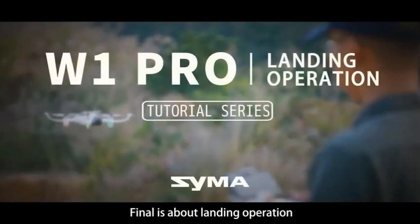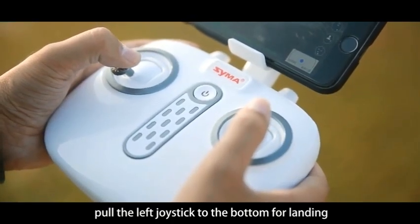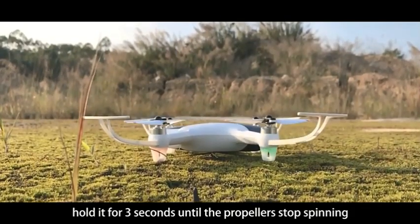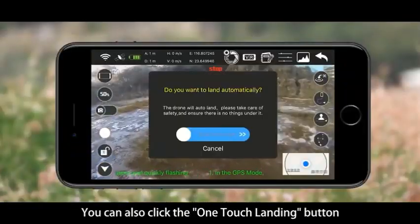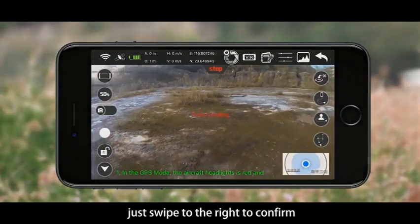Finally, the landing operation. Pull the left joystick to the bottom for landing. Hold it for 3 seconds until the propellers stop spinning. You can also click the triangle button at the left bottom corner for one key landing. Just swipe to the right to confirm.